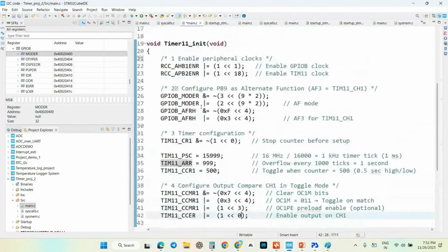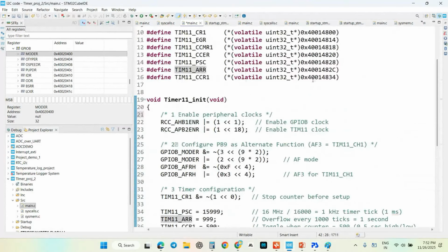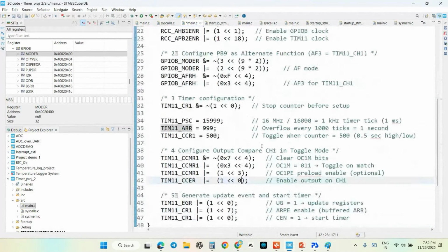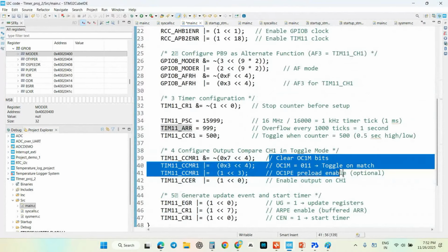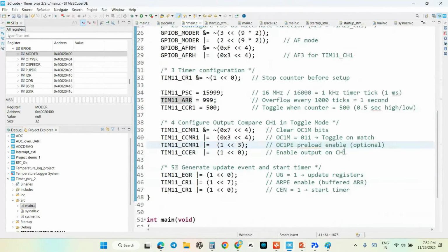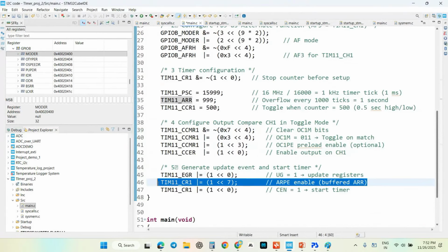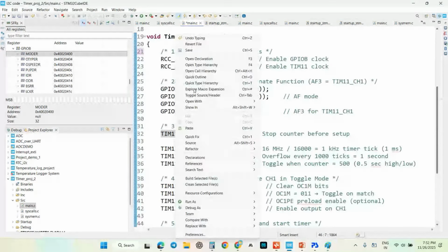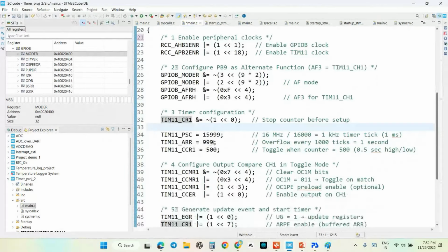So you just go to each and every register address. First of all, write the address, and then you clear and set the bit for everything, as they have given step by step. And finally, you have done this well. Set the auto reload register one. Previously, I told you it has to be enabled because you are using it here. That's fine. They have set the value.